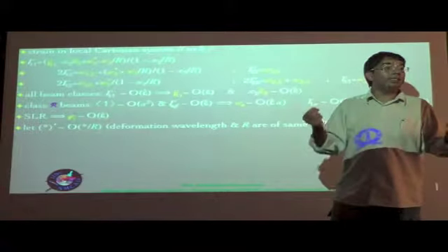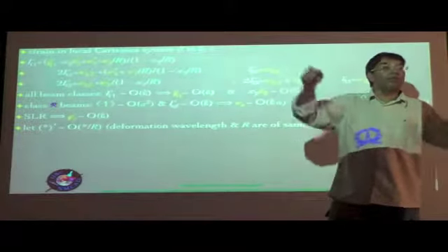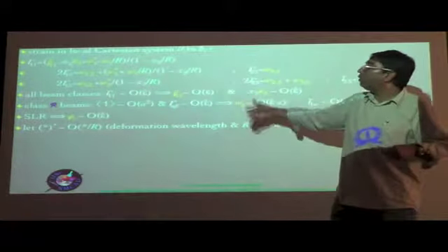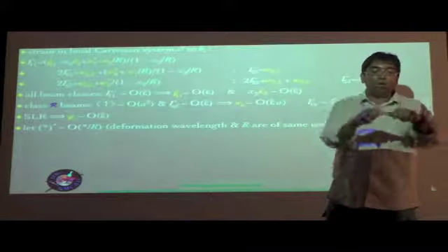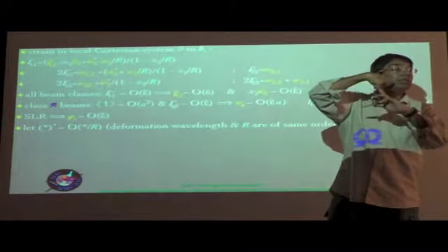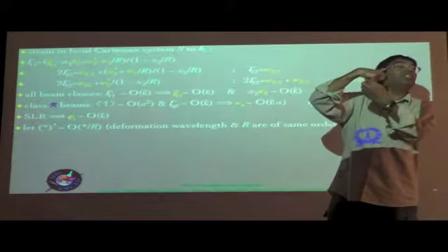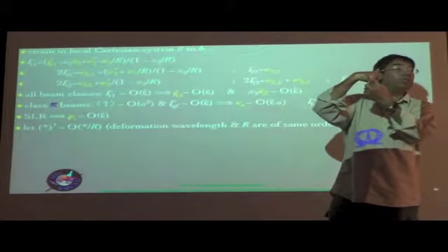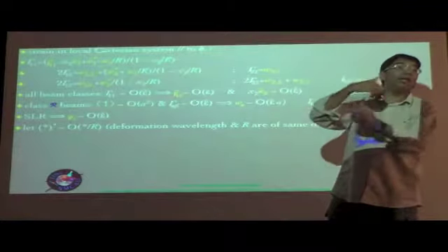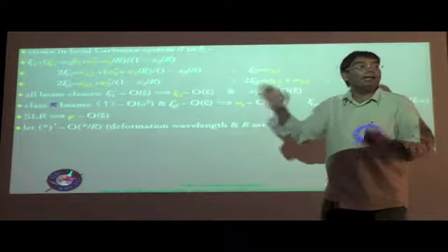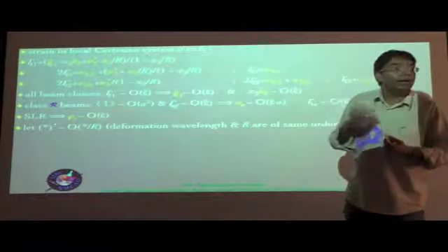Both of these quantities, the length of the beam and the radius of curvature, are things that you know a priori. A situation would be very different from this, for example, if you had a beam which was bending around itself, a typical example that I've been talking about in many situations. In that case the initial radius of curvature would be of the same order of magnitude as the cross-sectional dimension rather than the length. For that you would have to have a different kind of theory taking that relationship between L and R into account.